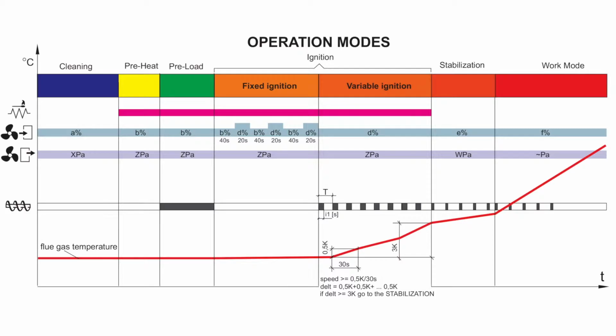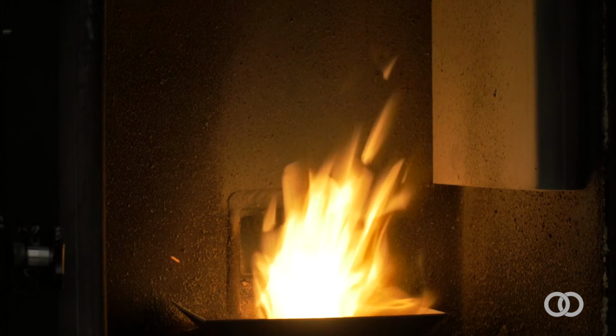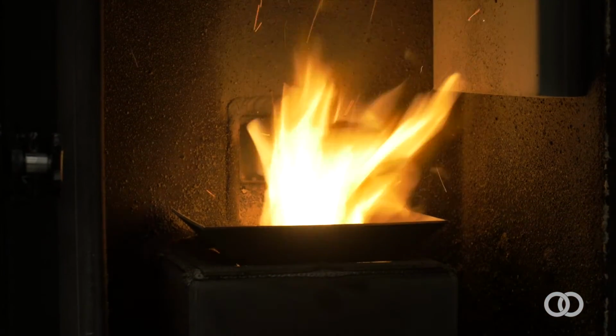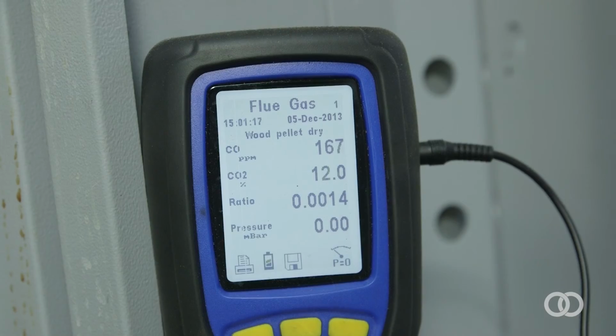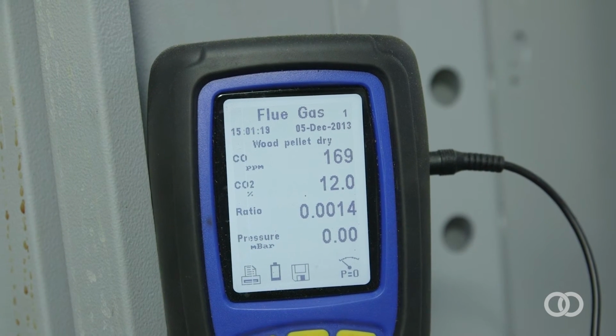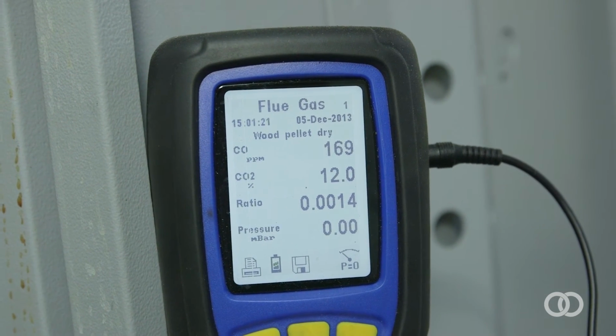You can also put in the energy density or CV of fuel here if you want to deviate from factory settings. The WCompact iGen controller, using an advanced algorithm, then calculates the fuel rates for each stage of boiler operation from 100% down to 30% power. This algorithm is often referred to as PID or fuzzy logic. It simplifies the commissioning process greatly and reduces the amount of human intervention in setting up the boiler.